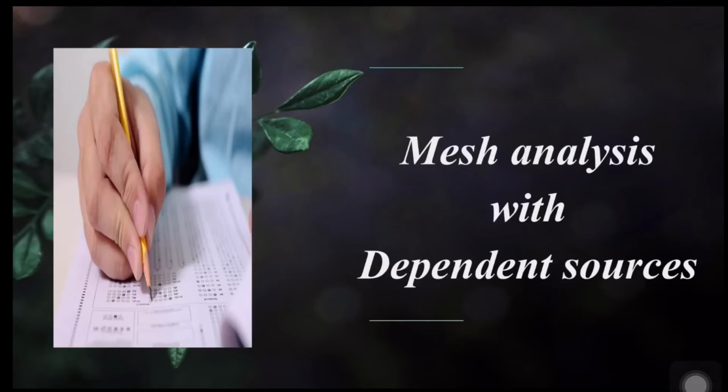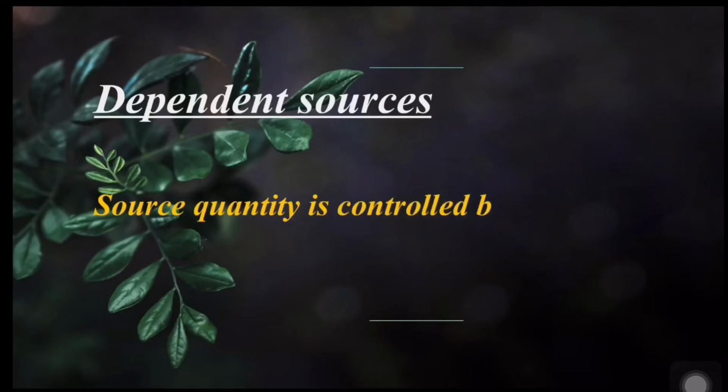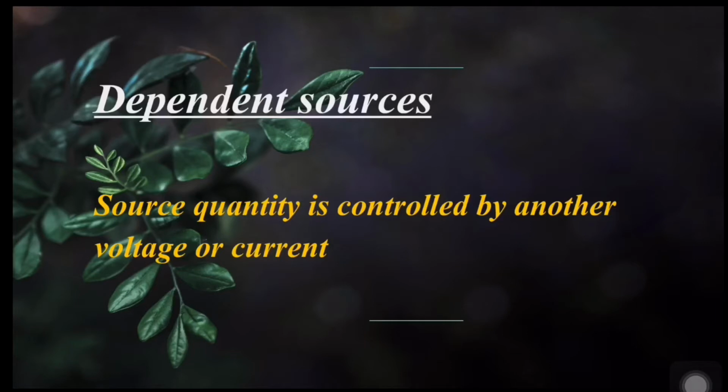First of all, I would like to ask you something. As I told you earlier, in this session we are going to learn how to perform mesh analysis in a network consisting of dependent sources. Do you know what is a dependent source? Any idea? Alright, in dependent sources, the source quantity such as voltage or current is controlled by another voltage or current that is defined at some other location in the network being analyzed. Got it? In other words, dependent sources are the sources where the source quantity is dependent on another voltage or current.